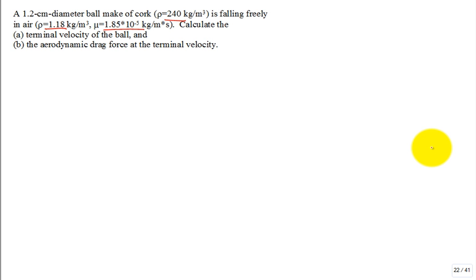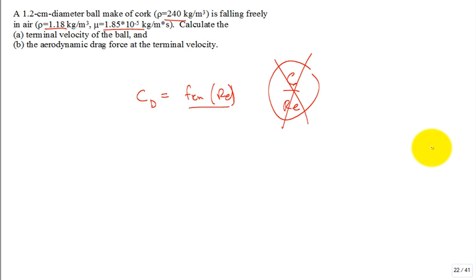How sophisticated do you want to be? Is that drag coefficient going to be a constant? If it's high Reynolds number, typically that's what you do. Or is it going to be a function of the Reynolds number? Or could it even be a constant over the Reynolds number? I doubt it, because that would be like Stokes flow. That would be really slow flow. That model probably is not applicable. It's probably some function of the Reynolds number to get the drag coefficient.